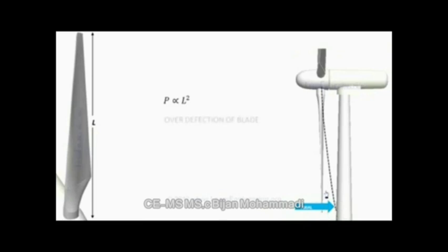With increase in blade length, tip velocity increases. Noise produced by the turbine is a strong function of tip velocity. So, it is not permissible to increase blade length after a limit. Another factor which goes against long blades is the requirement of huge mechanical structures, which leads to heavy investment.